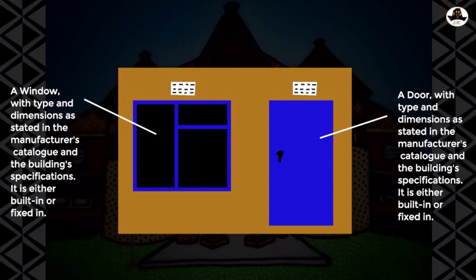And the parts of the window, we have the head, the frame, the windowsill, and the lintel above the window, which carries all the load so that the window does not carry load. The same thing with the door, it also has its own lintel. We are trying to make sure that these windows and doors don't break or have to suffer any loads on them. But that's basically a rough idea of the openings that we have.